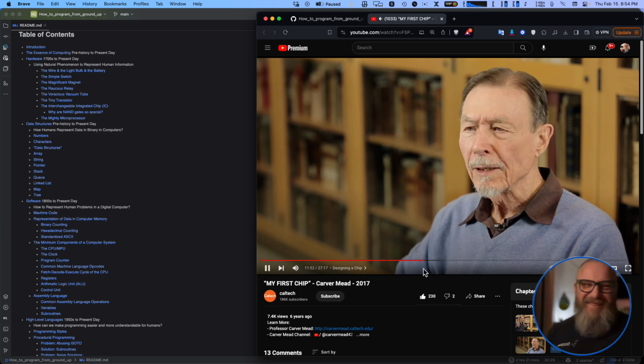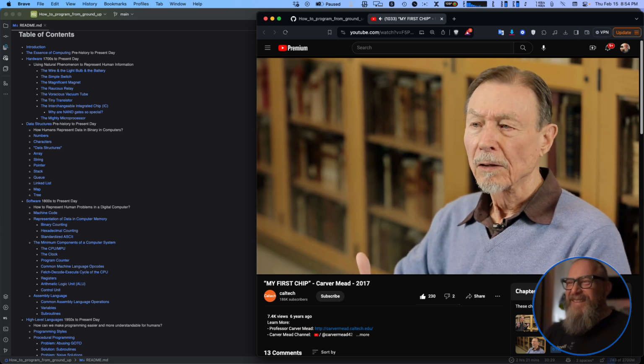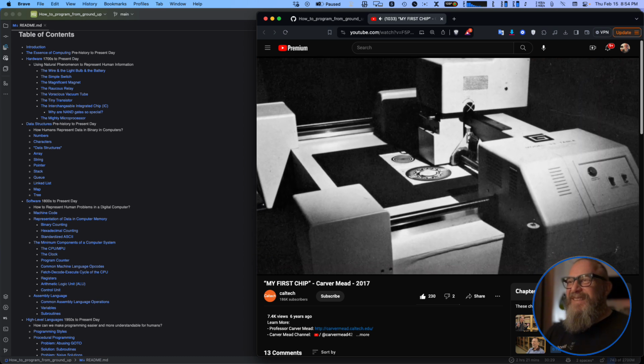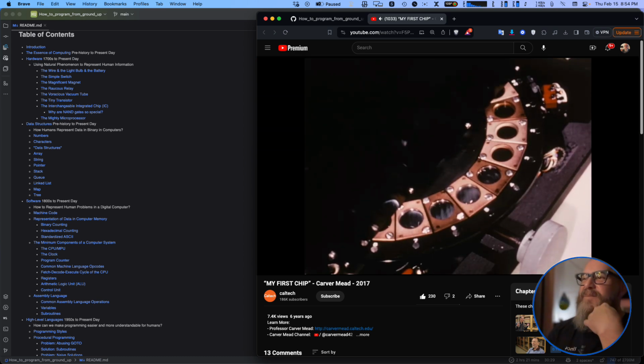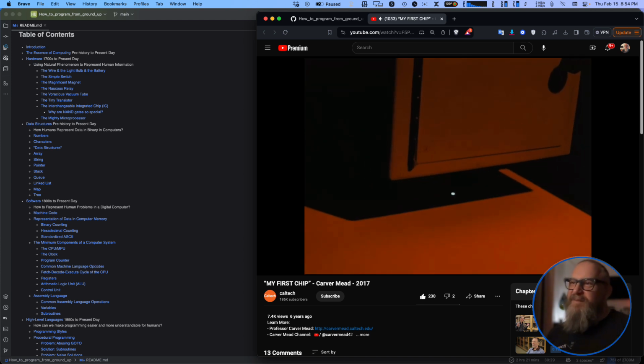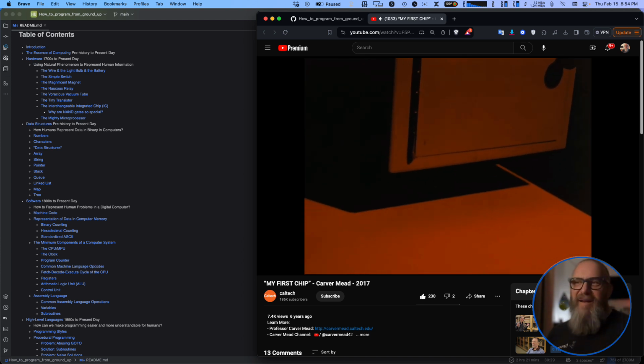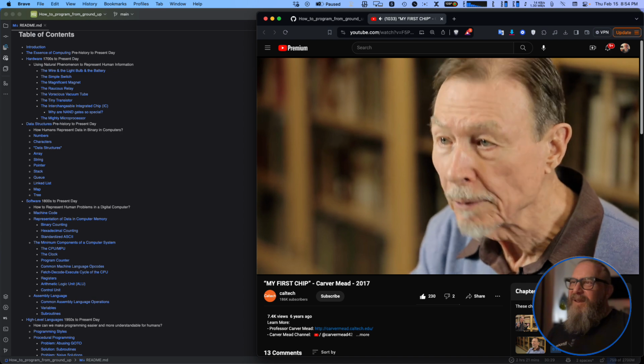Good words. Well, it turns out that the way everybody made their layouts was to use a thing called a Gerber plotter. And there were commands for this. It was called Gerber code. What it was, you select an aperture, then you go to where you want it to start, you turn it on, you draw from one XY position to another till you're at the end, then you turn it off. That's not hard. So I started writing Gerber code.